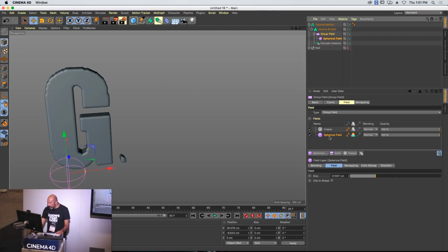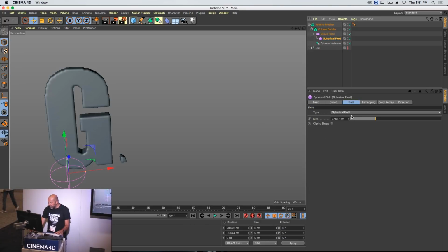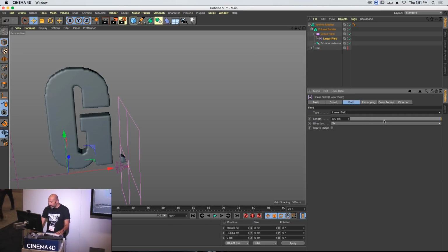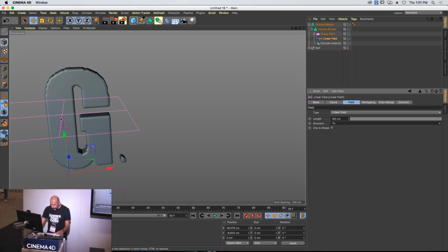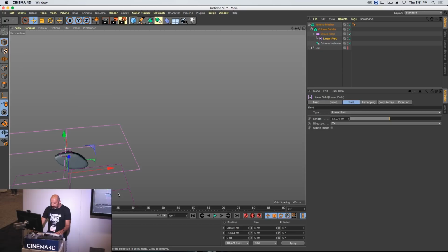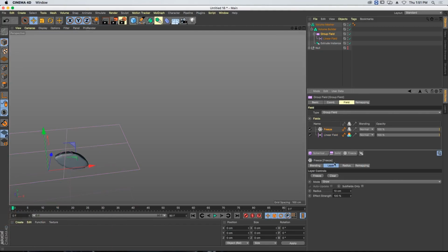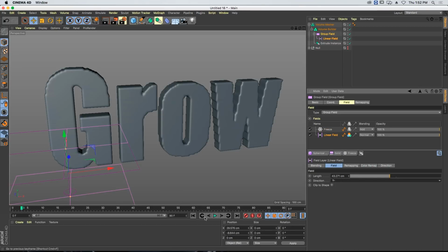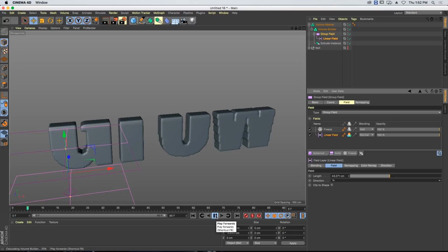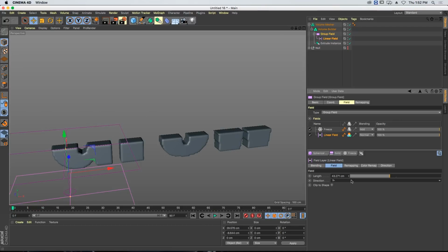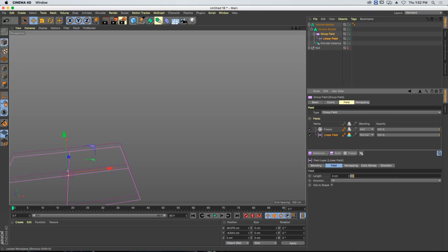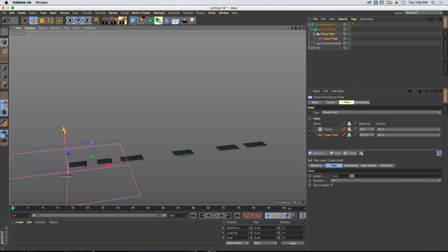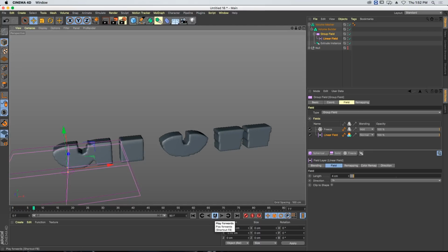What I could do is go here, let's select the field here, and say, you know something, I want a linear field. I'm going to set it to +y, make it smaller, rewind, always remember to rewind, and maybe I need to go to this guy and clear, freeze it, and see what happens. Oh, I'm going to set this to add. Yep, I just need to reverse my field to minus. And there you go. So now my seed is this layer here. I can control how thick I want it, and I need to make it, there you go. So this is my original seed, and everything grows in the same manner from that seed.